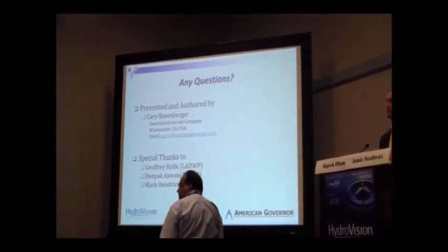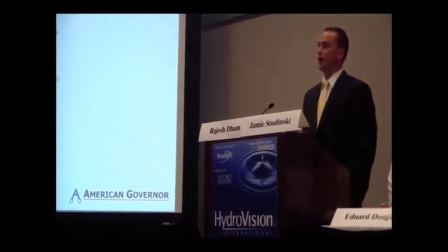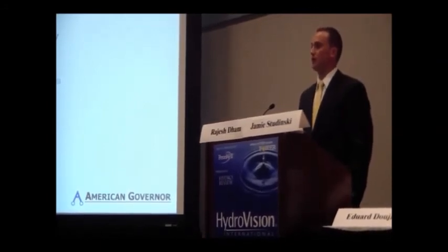Since you have such a good model of your system available, can you consider using a more sophisticated control scheme than a PID controller? Well, in our case with Castaic pump storage, we've found that we generally have the conformance we're looking for, and in that case, we haven't moved to any more advanced control apparatuses. Obviously, they're out there, and they all have pros and cons. So in our case, we thought it made sense to stick with a PID, although it should be noted that in that particular situation, those standard sorts of gains did need to be tweaked quite a bit in order to provide a stable system.